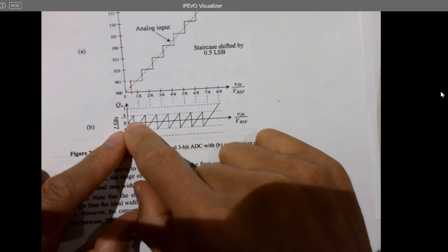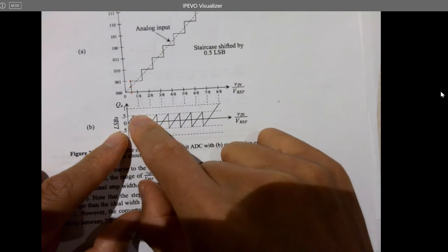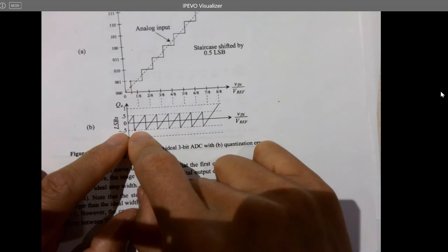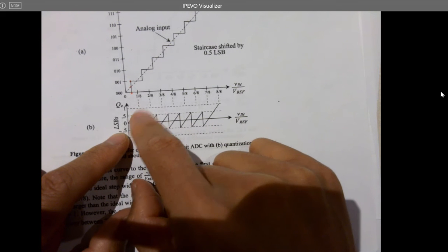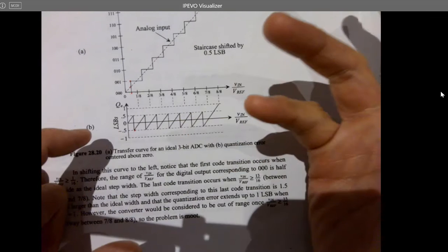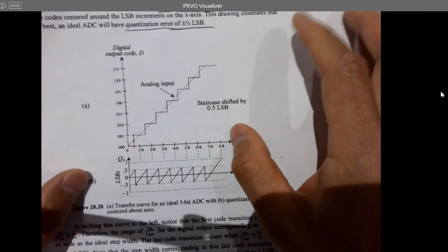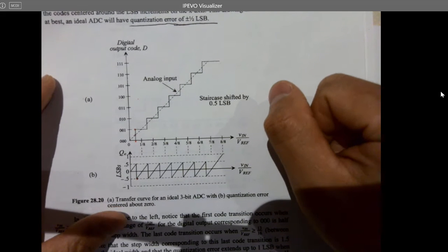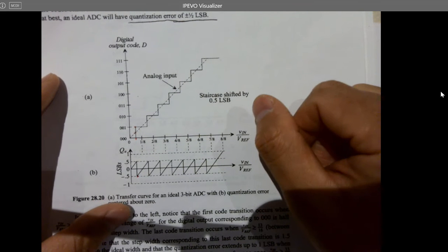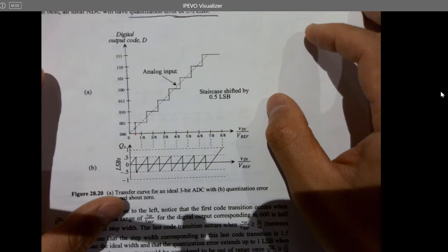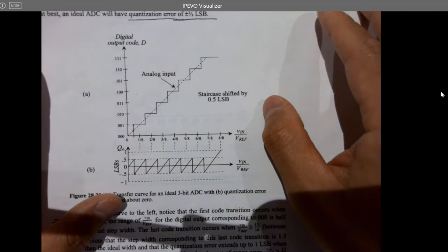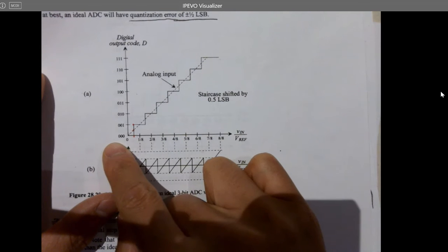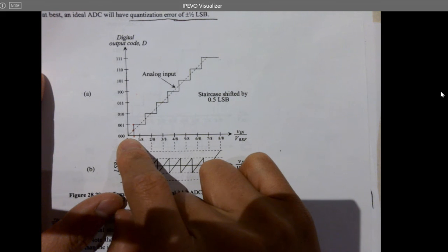You can see it's going up to 0.5 LSB and going back to minus 0.5 LSB. It never reaches 1 LSB. Just consider it as better performance. I'm also thinking about how to implement this on your SAR ADC. I can probably find a solution that can boost the performance of the ADC. They are all similar, based on LTspice schematics, and we have done that design in the summer. So I'm going to think about how we can shift it, so it's going to start from half LSB instead of 1 LSB.